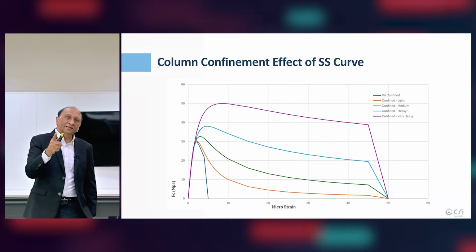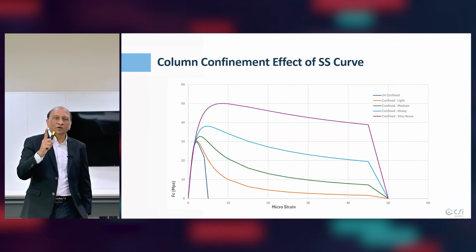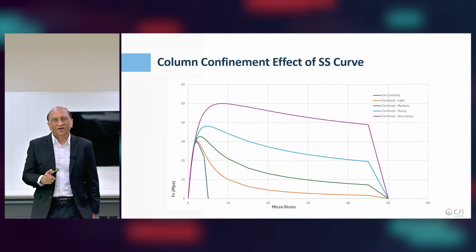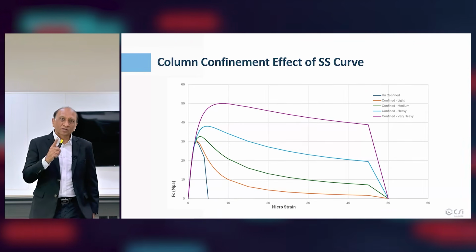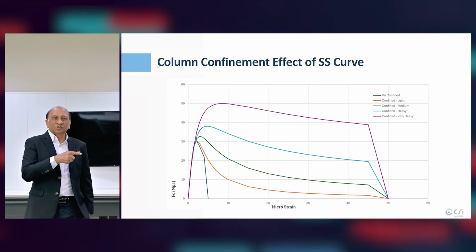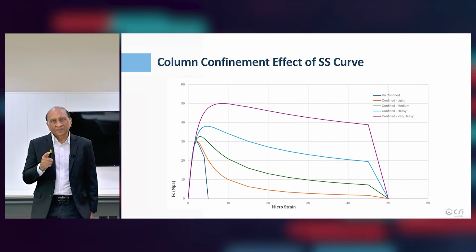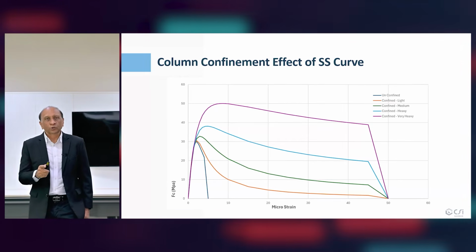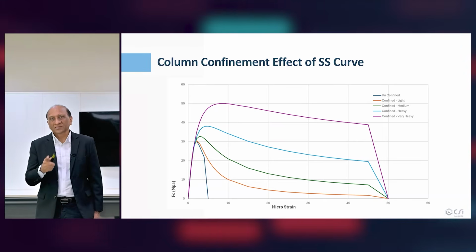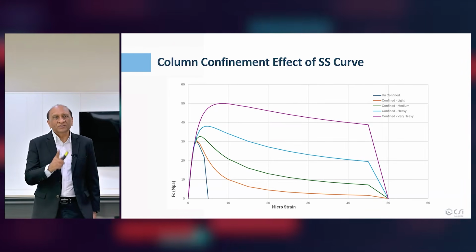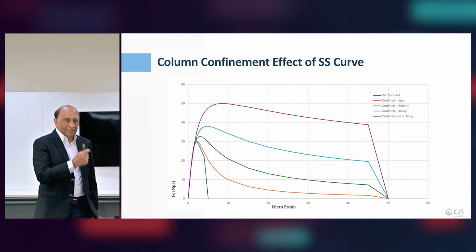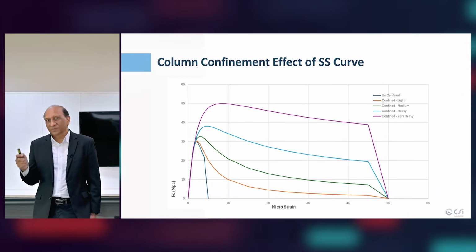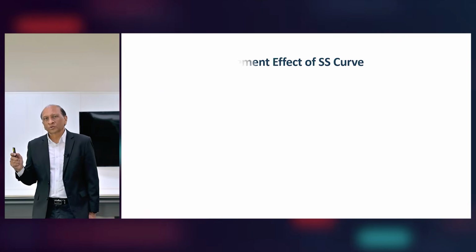Now you can see here that the failure strain of concrete is as high as 0.05 or 0.04, not 0.003. So confined concrete can take strain much larger than the capacity strain that we use. That means actual sections, column and beam both, have a much larger capacity than was predicted by the strength equation, because that was based on a strain of 0.003.